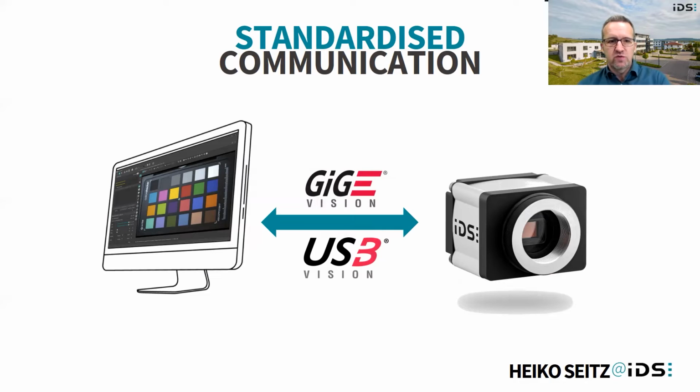The device-related software components like drivers or transport layers, as they are called today, now mediate between the camera and the user application with the uniform programming interface GenICam. This generic interface for cameras, short GenICam, now describes and abstracts access to all available camera functions across manufacturers and transport protocols. With the standard feature naming convention, the range of functions, function names, and camera behavior have also been defined and standardized.